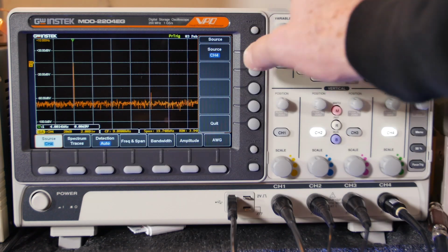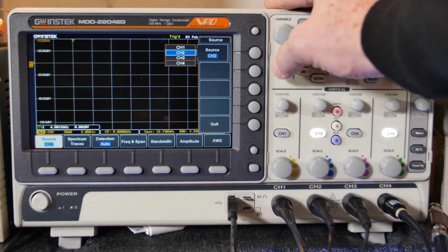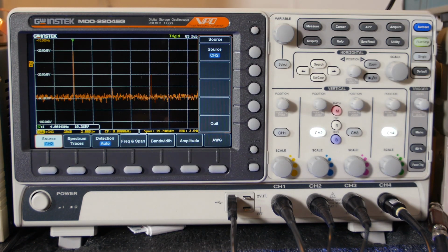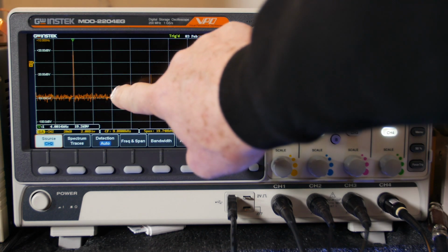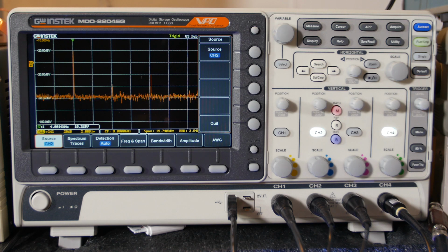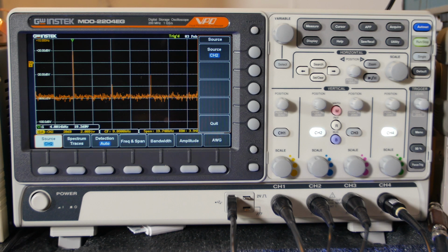Okay, now let's go look at the output again and see if they went away. Yeah, see, it amplified this guy, and this guy, there's a little bit of a signal there, so I think it's still kind of there. But alright guys, that's looking pretty clean. My THD meter right now has gone up a little bit. It's saying 0.889. So it actually has gone up a little bit.